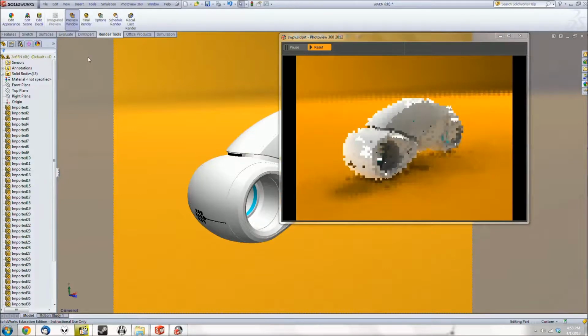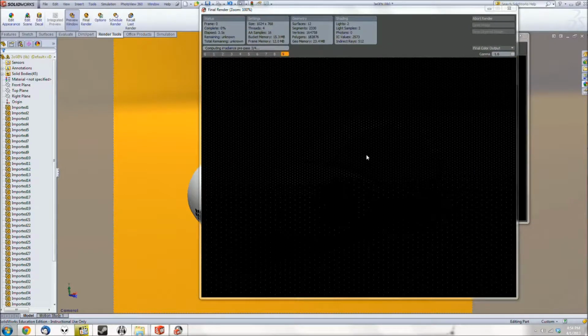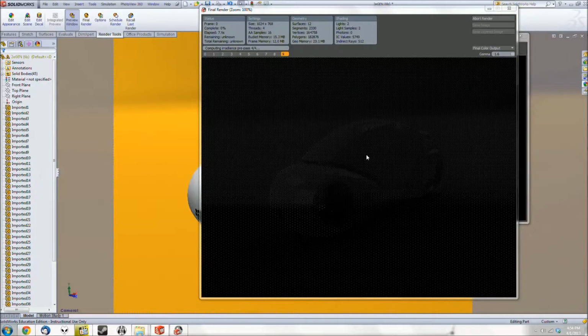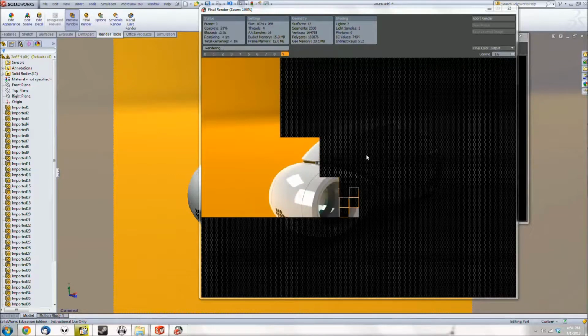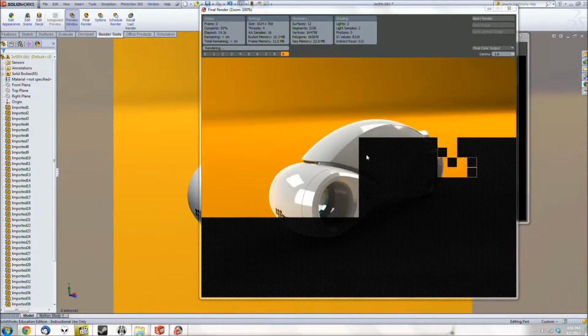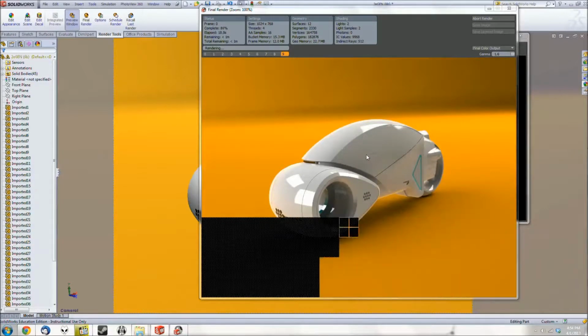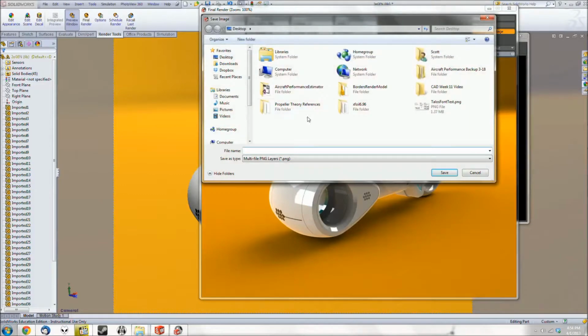Once you have that set up and it looks pretty good in your preview, just say final render, and it'll go through and do some pre-pass stuff relatively quickly. Then once it's done with that, you'll see it'll have 4 orange boxes that show what each core is working on at the time. I have a 4-core computer, so it's doing 4 of those at the same time. If you have 2, it'll do 2, 6, same kind of thing. So that's pretty quick. Once it's done with that, you can just click this Save Layered Image button.